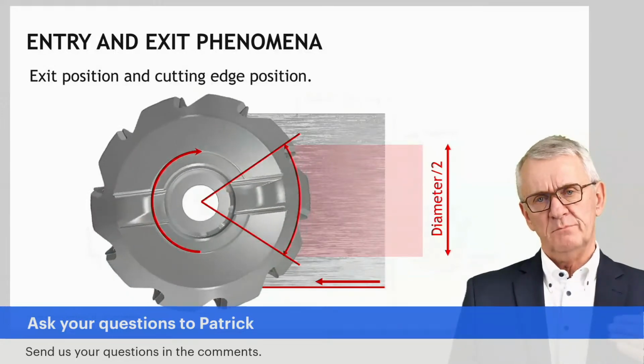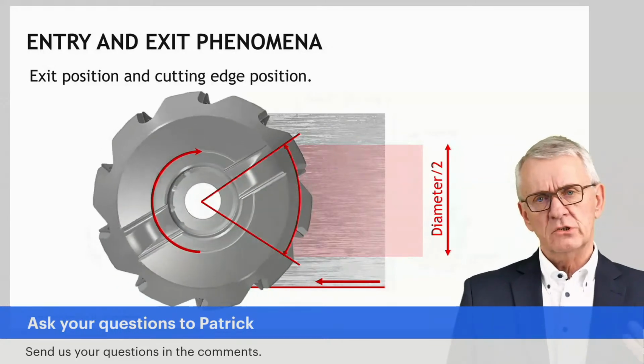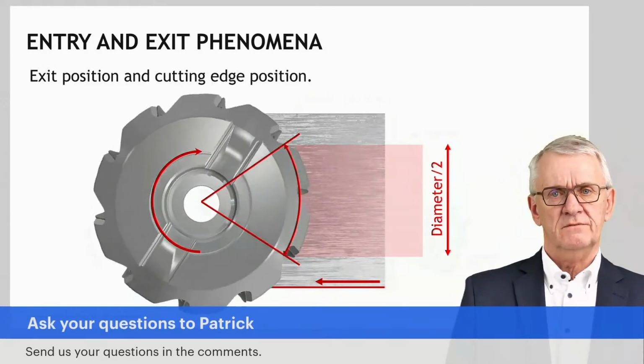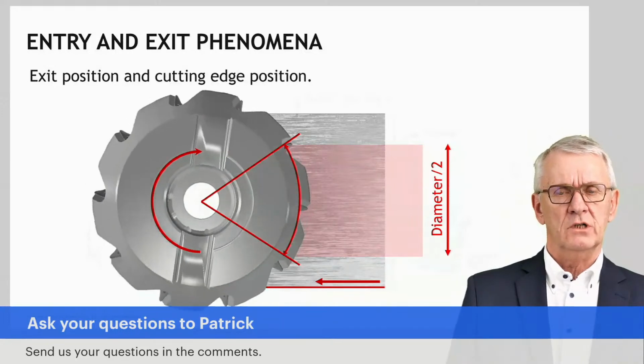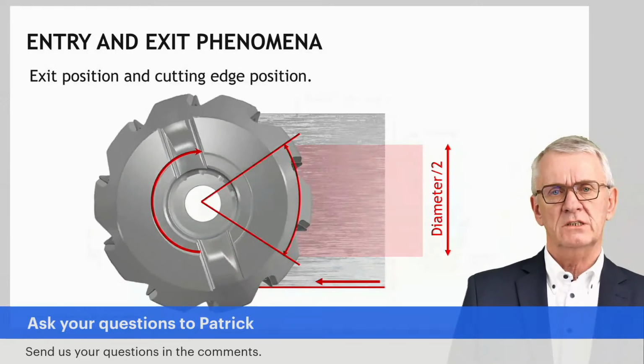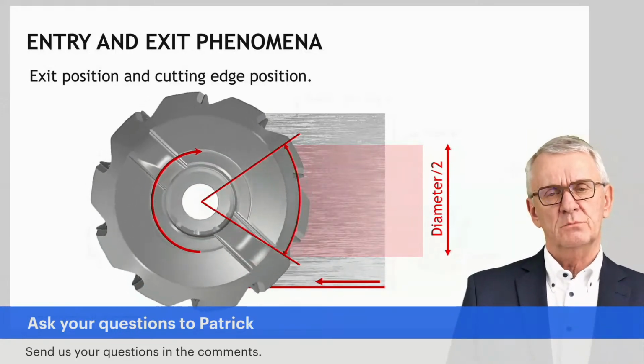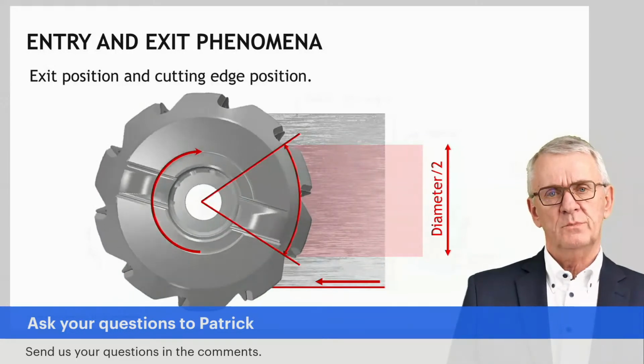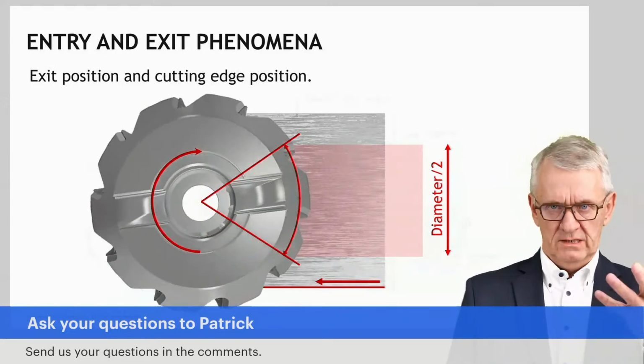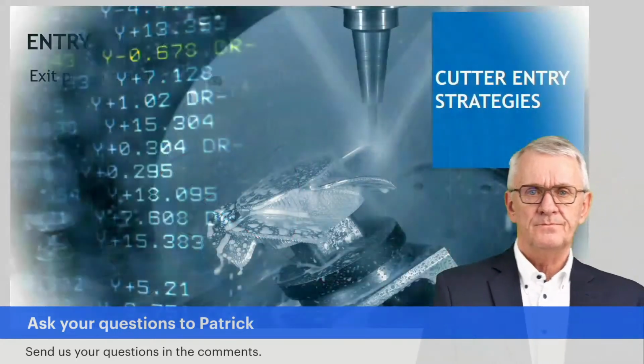It should be above it, but that's not so nice, as that is very firmly up milling, and we don't like up milling. See, one of the things I already said. Down milling is much more preferable, so the workpiece should be downwards in this picture here.